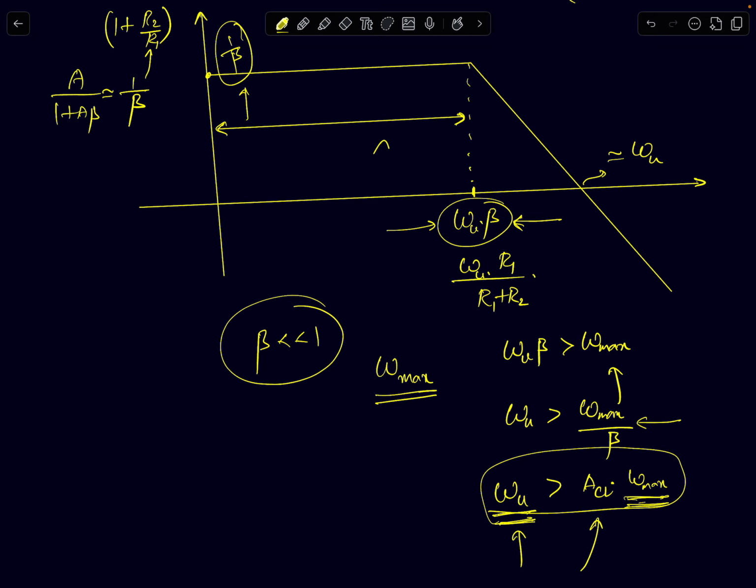Okay, so this is something to keep in mind. Generally, if you are increasing the DC gain, your UGB will also be higher, because UGB is the product of your pole times the DC gain of the op-amp. So if you are increasing A, UGB will also increase. I haven't in fact uploaded any video on my op-amp series lectures yet. There we will discuss in great detail, whenever I get time, how you set all these things. There are several trade-offs there, so we'll talk about that.